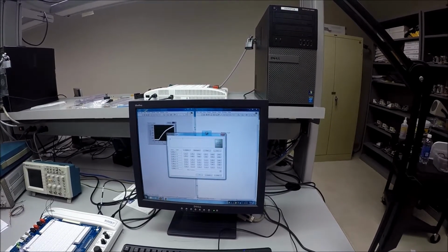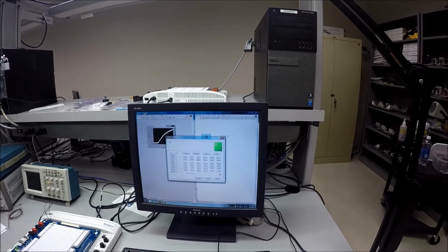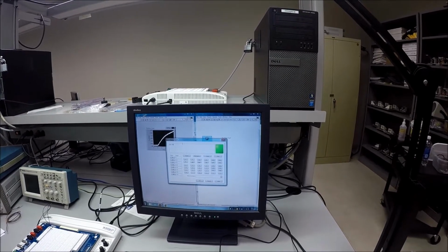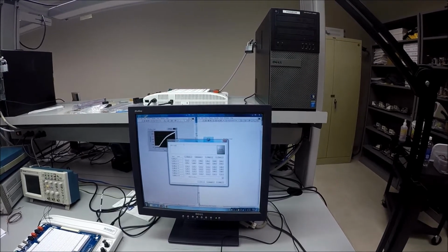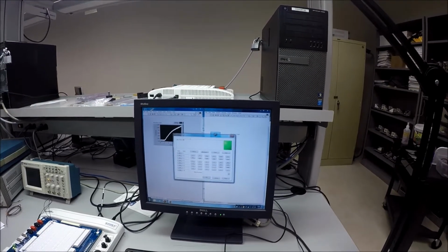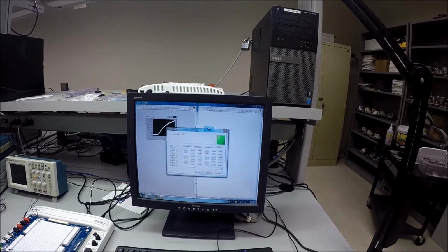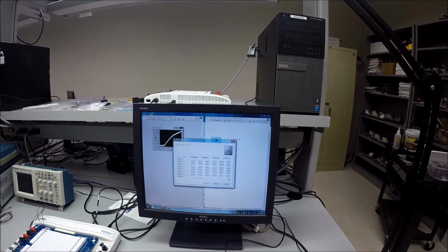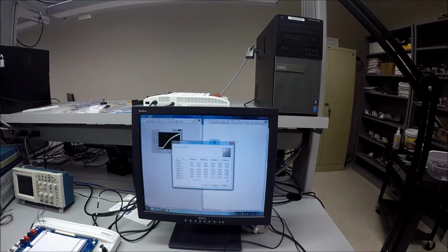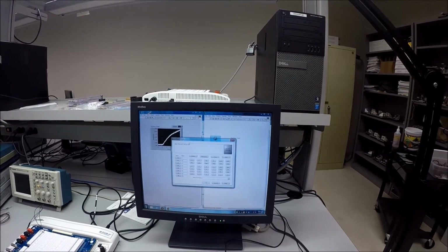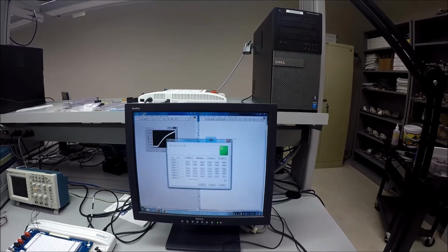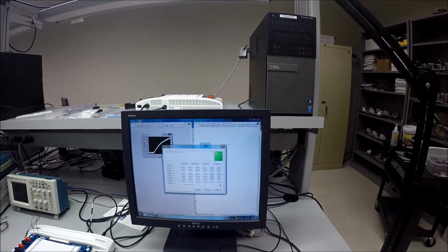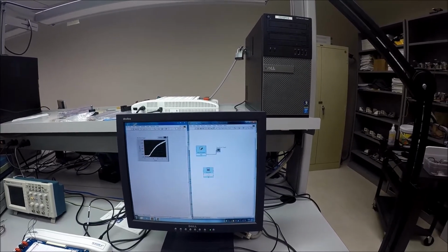We have something like (98.6 minus 75) over (2.07 minus 2.42), times (V, which is our voltage, minus 2.42), plus 75. So this is just a linear interpolation of 2 points. Hit the OK button.